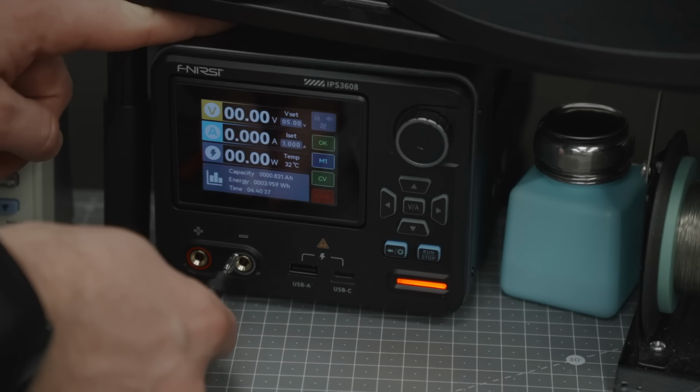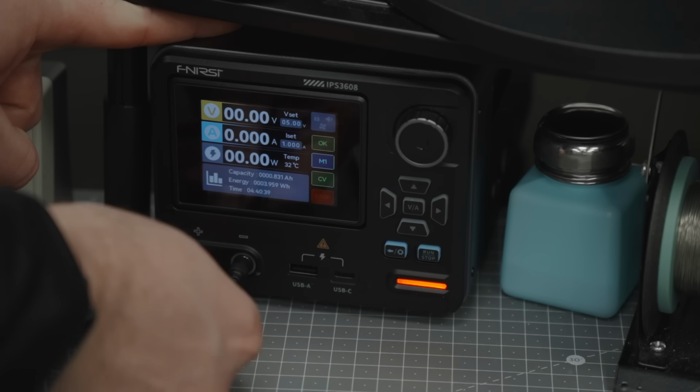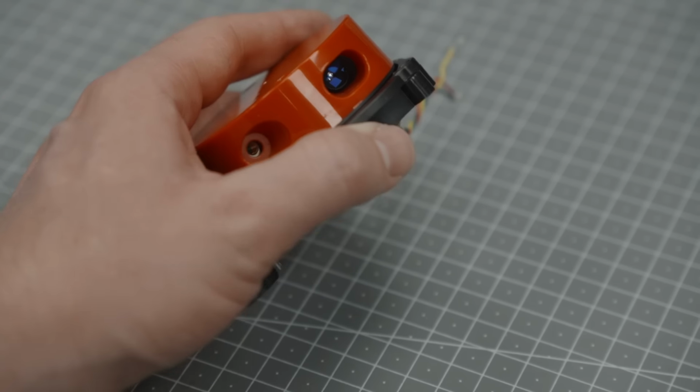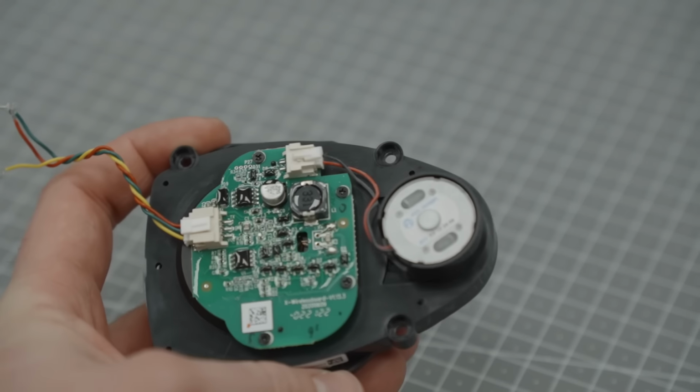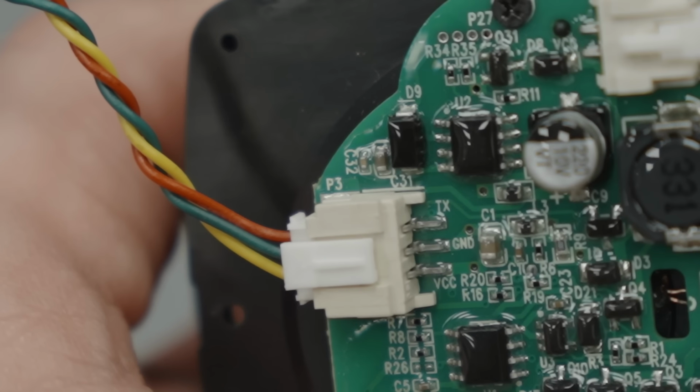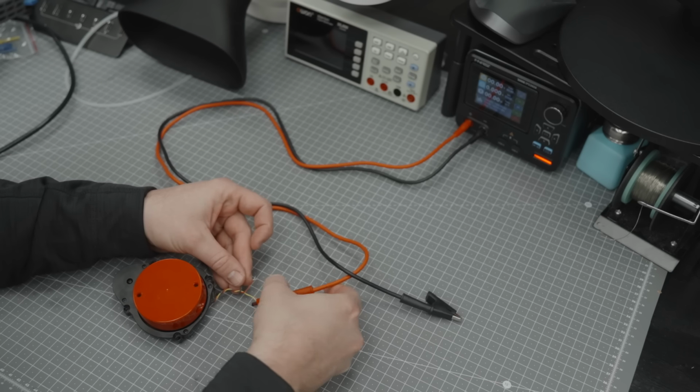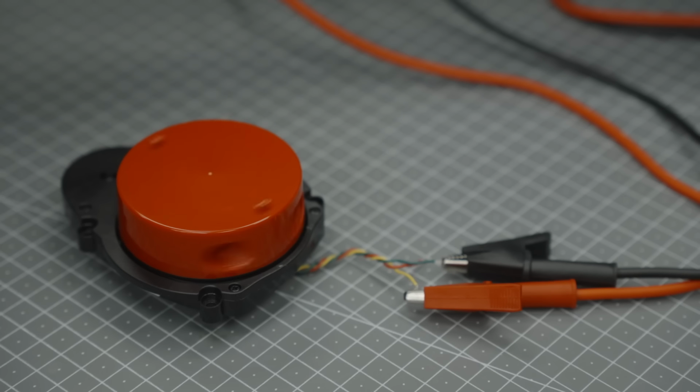Alright, so let's move to a fun little project so we can see how the protocol decoders in PulseView work. I salvaged this LiDAR unit from an old vacuum robot, and it would be nice if we could read its measurements. It only has 3 wires going to it, which are labeled VCC, GND and TX. I would suspect TX just being UART, but let's take a look.